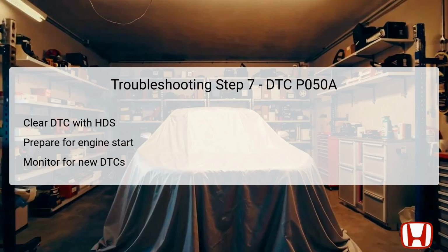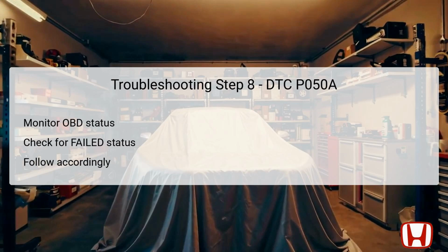This step serves to refresh the vehicle's diagnostics and allows for the identification of any persisting problems that could require additional steps or repairs. Following the engine start, the next step is to monitor the onboard diagnostics (OBD) status via the HDS for DTC P050A. If the HDS indicates that the status has failed, it signals an ongoing issue requiring further diagnostics.